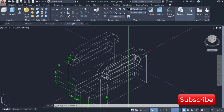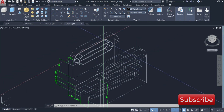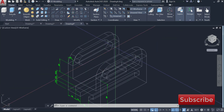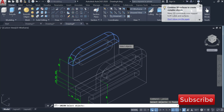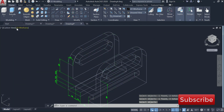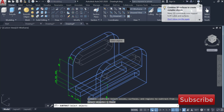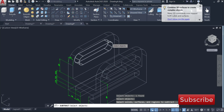So we need to remove this part. First, you need to join this shape to the big geometry. Click union. So click this one, click this one, enter. So we have joined this. Now we need to extrude this, but we need to cut, so we'll have to use the subtract command. Select the base model and then enter. Select what you need to cut